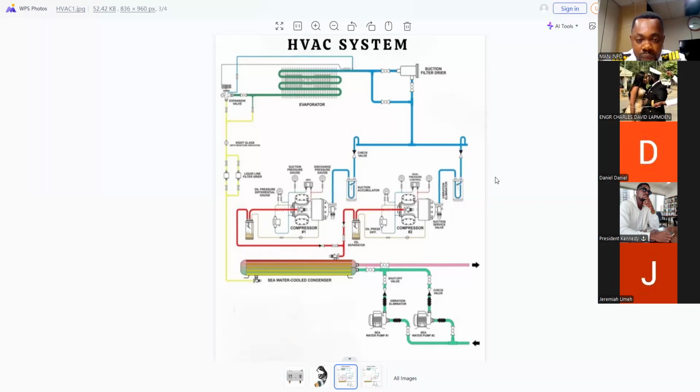Okay, I can see your condenser has different colors. Can you quickly explain why it has different colors? Secondly, what temperature difference should call our attention? That is, the temperature difference between the seawater inlet and outlet of this condenser, a temperature difference that shows fouling or clogging, with typical figures.